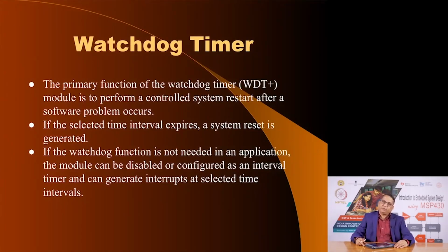Watchdog timer is a very important peripheral. It is actually part of a general purpose timer, which can function either as a timer or as a watchdog timer, and we can choose which mode of operation we want that timer to operate in. The primary function would be as a watchdog timer, because there are other timers available which you could use for measuring time. This particular timer is often dedicated for use as a watchdog timer.